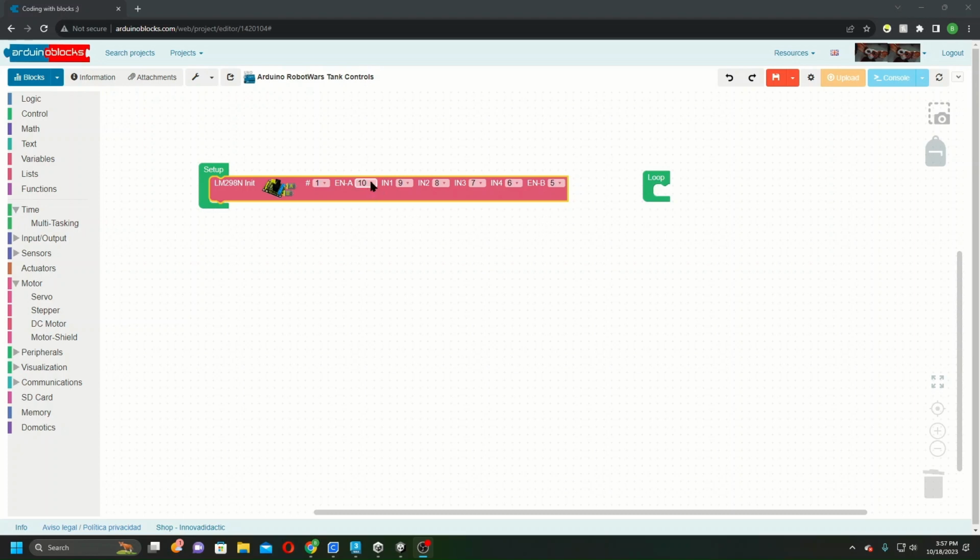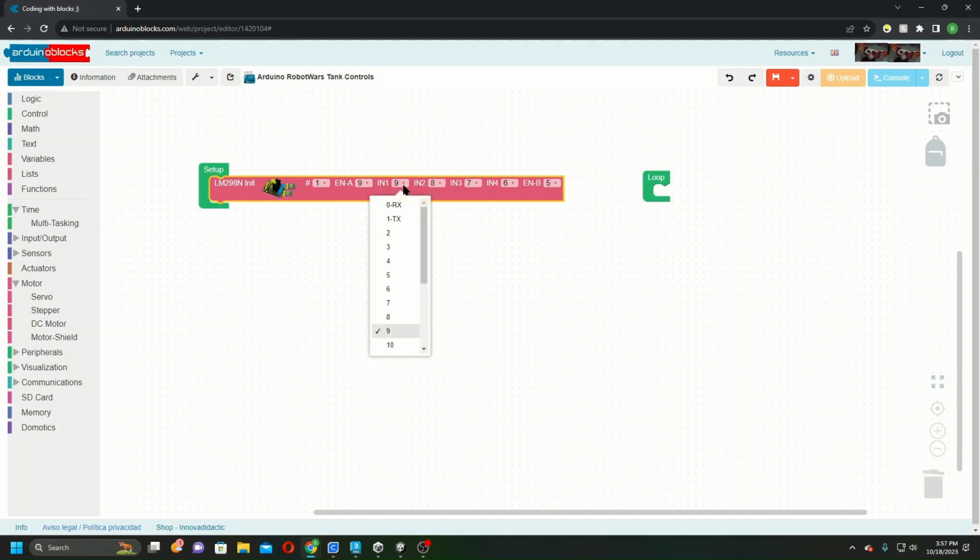For our example here, I'm going to change this one to 9, this one to 5, 4, 3, 2, and 10. So these numbers are not 100% random. I'm skipping pins 1 and 0 because pins 1 and 0 are used for our USB communications, and if we can avoid using them, that benefits us. So that starts off my numbering from pins 2 through 5.